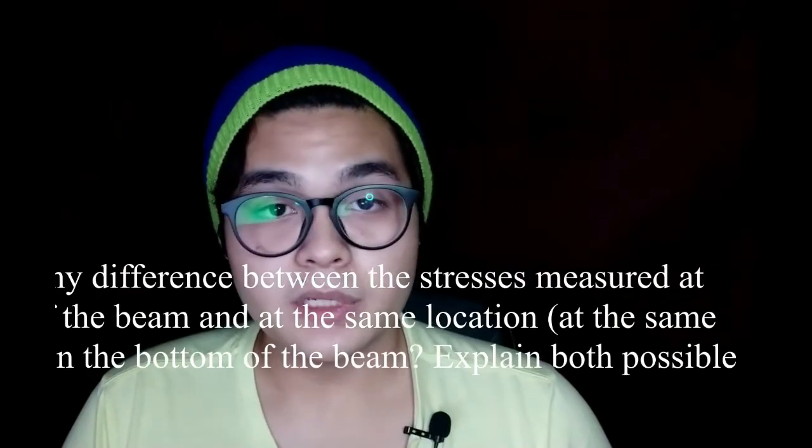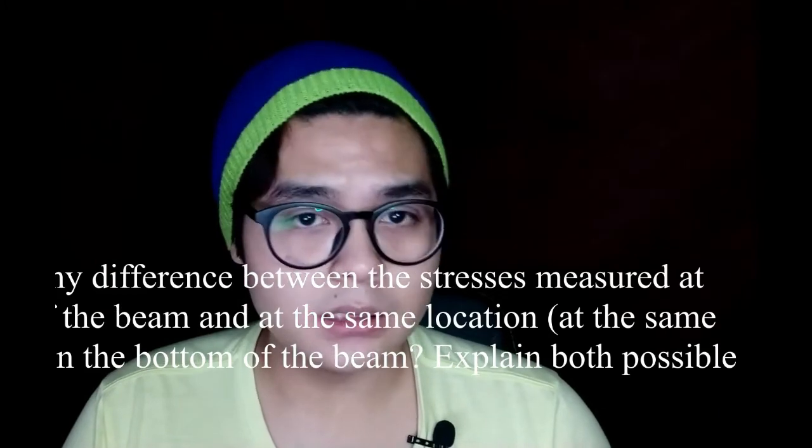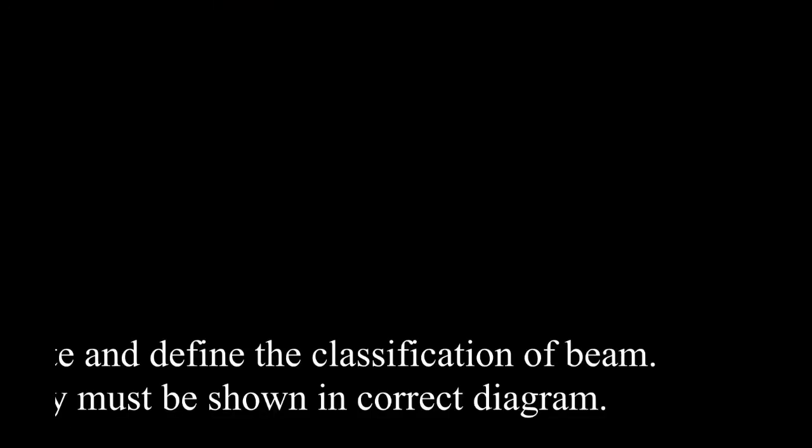Number 4. No, because compression will occur when the bending forces happen on the top of the beam, while vice versa at the bottom of the beam. This is possible if the y, which is the distance from the neutral axis to the point of stress, and M, which is the bending moment at the section, reach their highest.